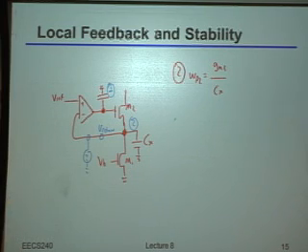Yeah, exactly. So the whole point is, remember, when you're trying to make one pole dominant versus the other, it means you have to put it at a much lower frequency versus the other to ensure that you get sufficient phase margin. Now, okay, maybe before we do that, just to be totally clear, where is that pole going to be at? And let's just assume, by the way, that the amplifier that I drew there has some output impedance, RO. Where is that pole going to be?